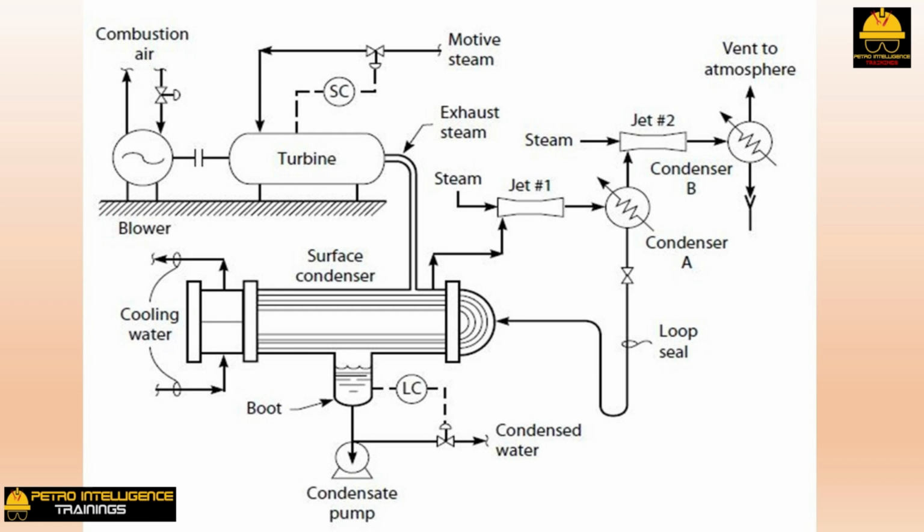The final condenser hurts the upstream vacuum. The final condenser increases the discharge pressure from the secondary jet and thus makes the jet system work slightly harder to expel the non-condensable gas load.